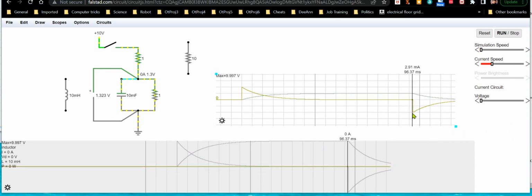Okay, now you can see right here the current is negative now, but what that means is the capacitor is discharging, because the current has instantly gone very high negative, and again the current is not going to be this high ever again. It's going to diminish from that 10 amps that it's basically starting at, and fall to 0 amps. And more importantly, the voltage is starting at 10 volts, and then falling down to 0 volts. So basically the voltage is falling as the current is also decreasing.